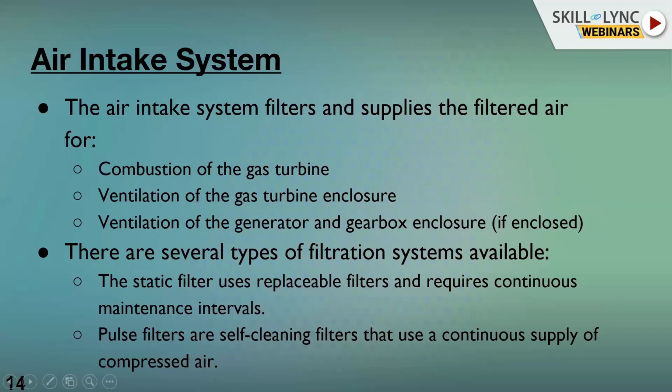So what is a static filter? A static filter is a filter which you need to replace when the particle buildup is more than the limit. So it requires continuous maintenance intervals. This is simply like your typical AC vent or a cooler vent, where you have to clean the filters every time to ensure it is going to provide the output as desired.